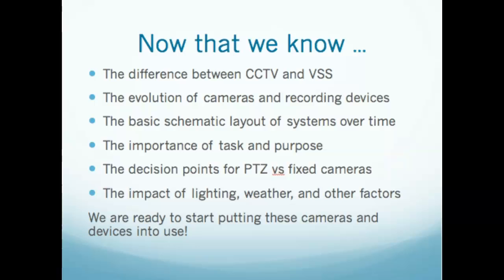We talked about some decision points for PTZ versus fixed cameras. PTZs sound really cool, and they are really cool. And in the right application, they're fantastic. But a fixed camera will always be where you need it to be when you need to review footage or when you need to watch something. So always apply that logic. If I absolutely need to see this thing all the time, then it's a fixed camera, it's not a PTZ. You can always go with multiple lenses inside of the same housing as well, and you'd have a fixed camera that pointed 3 or 4 different ways. You'd have 3 or 4 fixed cameras inside of a single dome.